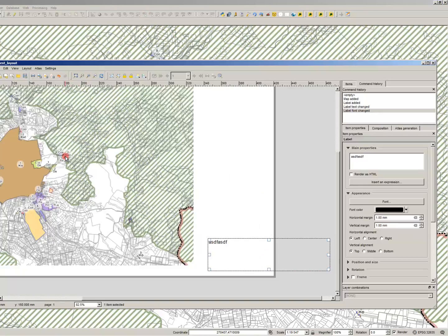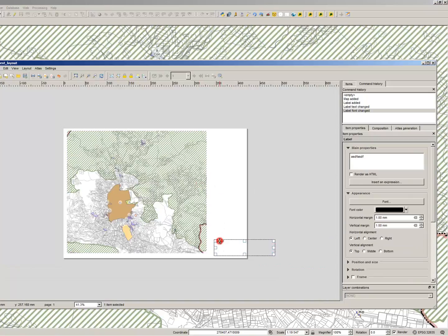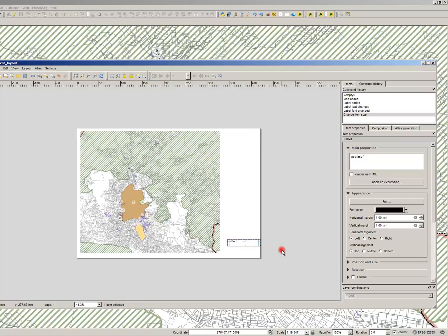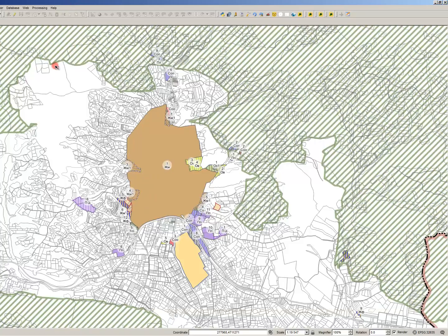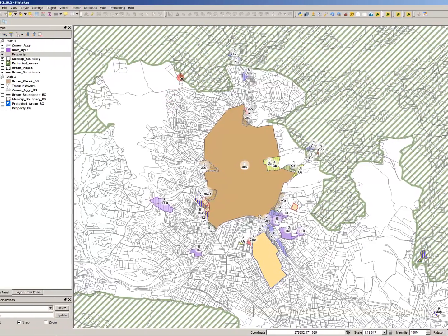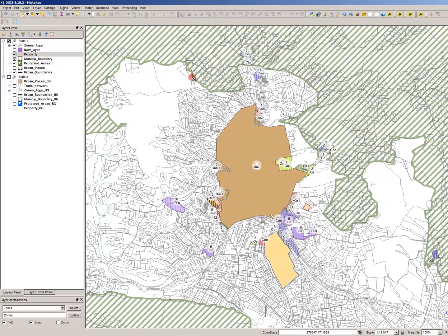But it saves a lot of time, and sometimes it saves also the types of layers you used in your project. The fifth mistake is not saving your layer styles, and it can be a very trivial layer style like this one, municipality boundary.